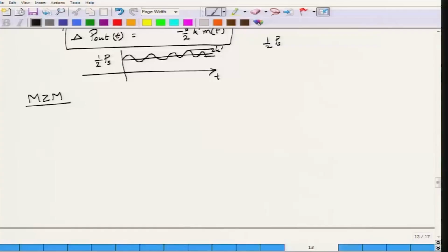So, in order to do that one can either have a pulsed laser by itself, but that would be a different approach. But if I have a continuous wave laser, then I can use the Mach Zehnder modulator to generate optical pulses. Okay. In order to see that one, let us go back to the power transfer function of the Mach Zehnder modulator. So, I have as a function of the difference signal ud of t. The power transfer function is of course something that we have seen here. So, this is the power transfer function.